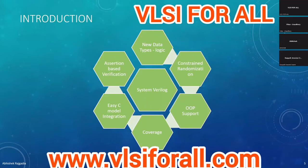By constraint randomization, what it means is that you randomize the inputs. Like if there's an adder with inputs A and B, we'll randomize them. It can generate 0, 0, or 0, 1, or 1, 0, or 1, 1. We don't know, but we just call a function randomize and it will generate one of the possible combinations. And by constraint, we mean within the specification of the design.